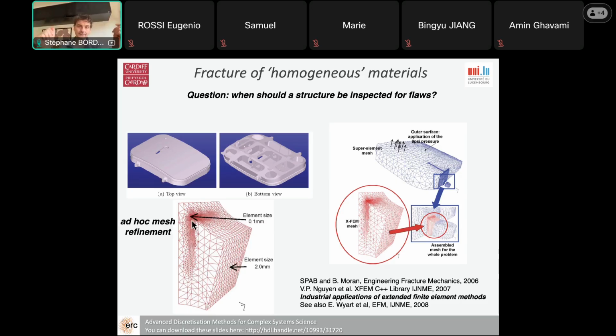It's the worst possible case, because if you have more stiffness around, the rest of the stiffness will prevent the crack from growing. It will somehow control the growth. But if you have nothing around, there is no inertia, let's say, to prevent the crack from growing. It's not exactly inertia, it's a bit of a fake comparison, but you get the gist of it, right? If you can constrain the crack because you have more structure around, it's going to be able to redistribute the load. But here you assume everything happens in a plane, and therefore there is no redistribution of the loads. Therefore, the case is really worse. So that's what we try to improve.